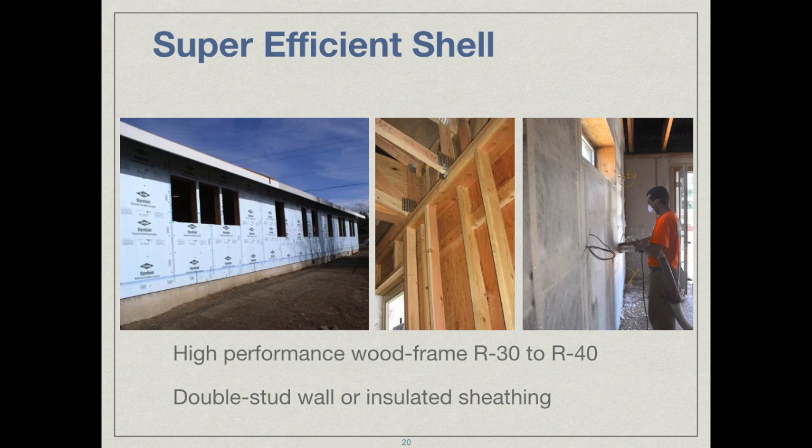It's well worth the little bit of extra money you pay in order to get a little bit denser material, a little bit higher R value in the cavity, and also a reduction in the air leakage.